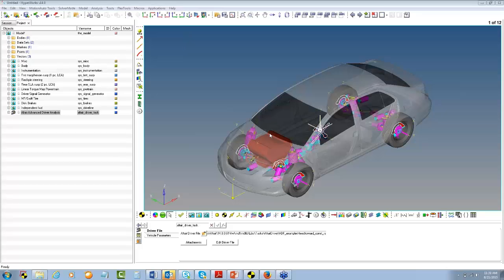Okay, so what should be the rebound travel? As you said, it should be around 5 inch, but would 5 inch be a greater value? Yes, it would be, and generally your rebound bumper should also not engage. This rebound bumper should come into the picture only in case of some ridiculous kind of suspension travel. Please don't take all these values as fixed, because I really would like you guys to design that, and that is what all these competitions are about. You can come up with a better value.